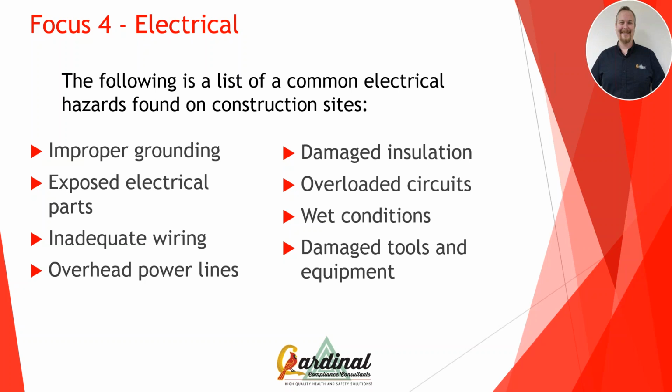What that is, where I have, let's say, a three-way splitter and an extension cord running to that. Well, sometimes, let's face it, three receptacles is just not enough. And if you ever put up Christmas lights, you run into that problem where you just don't have enough plugs. So you put into that three-way splitter maybe an additional three-way splitter. Well, if you keep doing that, eventually you're going to overload that circuit. That's going to create heat that becomes a fire hazard. And again, that's something a lot of people in construction just don't quite recognize.